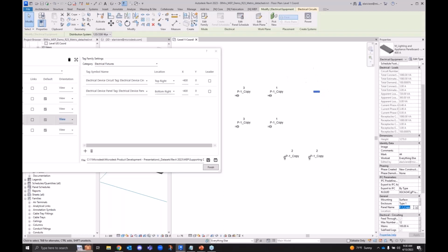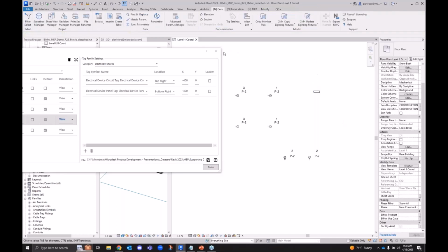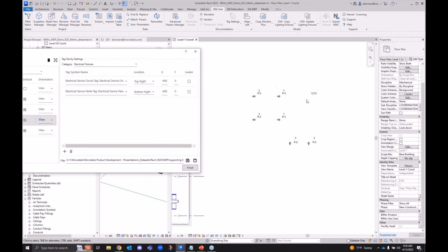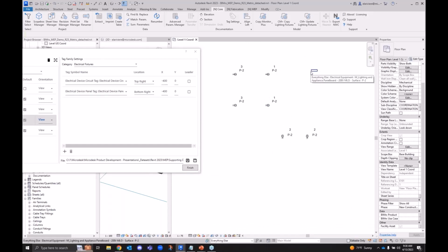This is not some text-based magic. We're not doing anything funny. We're not adding weird parameters to do this. We are actually creating an entirely new panel, new elements, and recircuiting those to the new panel in the exact same place that they were before. It is an incredibly, incredibly quick process to go ahead and take something that's typical and bring it around. And in fact, it doesn't even need to be perfectly typical, because you can bring it without hosting and then just move these items to wherever they belong after the fact, right?